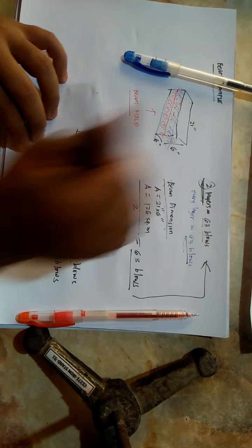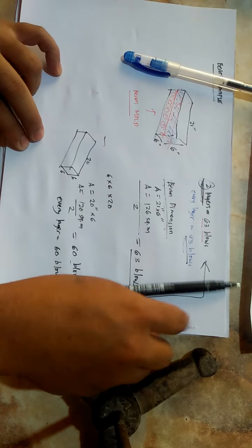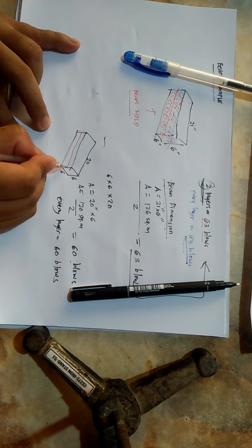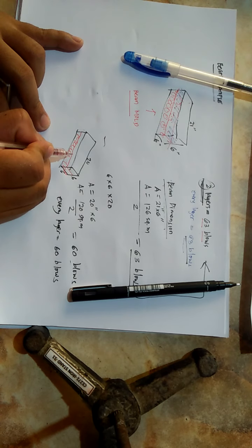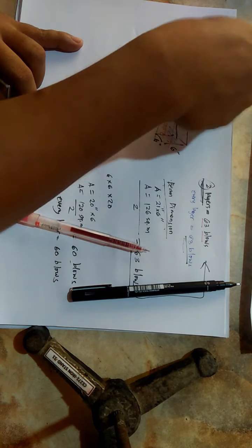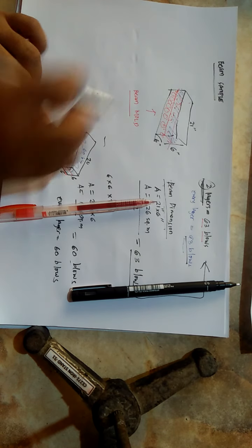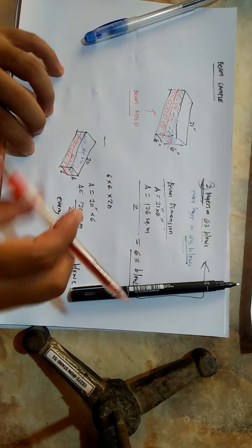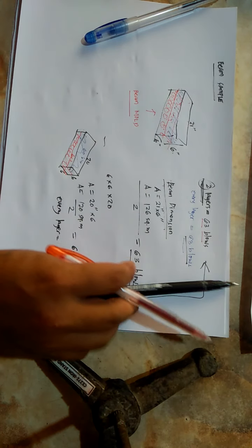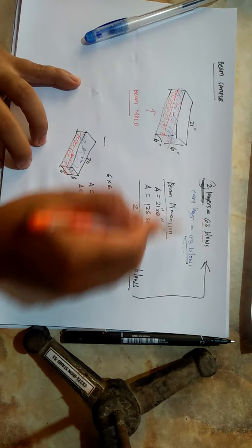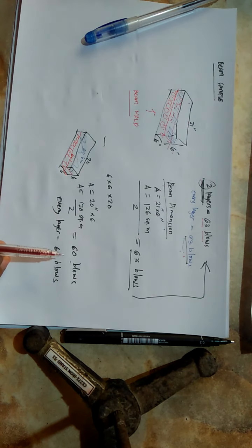Ang blows kasi dito, yun yung parang tinatamp mo siya. So, meaning to say, first layer mo dyan, lalagyan mo ng concrete, meron kang 60 blows. Sa second layer naman, meron kang ulit 60 blows. Pero kalimitan, ang dimension ng beam sample natin is 6 by 6 by 21. Kaya, in every layer, 63 blows, a total of 2 layers.